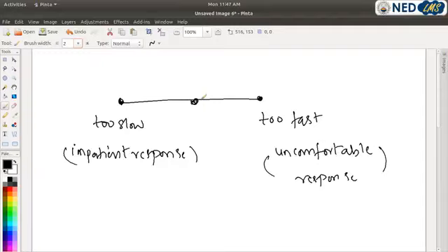Transient response is also important for physical reasons, as too fast response can damage the physical structure permanently. In this course, we will establish a quantitative definition for a transient response. We will then analyze the system for its existing transient response. Finally, we are going to adjust the parameters or design components to yield a desired transient response, which will be our first design objective.